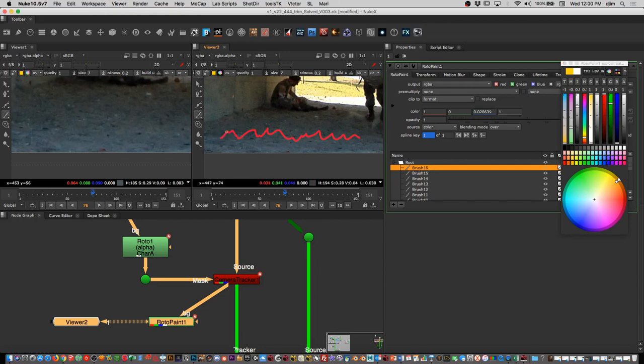So that means you're going to have trackers that are up here, down here, maybe in the middle, maybe all the way to the peaks of what you're selecting. So what is going to happen is that the actual ground plane that we create is going to average, and it's going to cross in between the average of all of those, not exactly through the points. Okay? So that's one thing you got to realize. If not, you're going to struggle trying to put that exactly where the points go, and it's not going to happen. It's just an average.